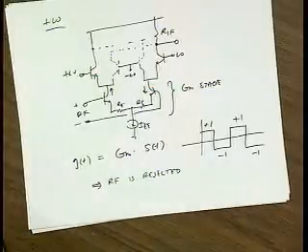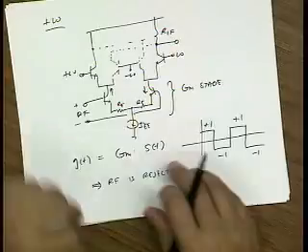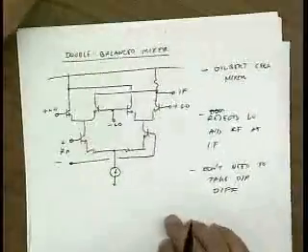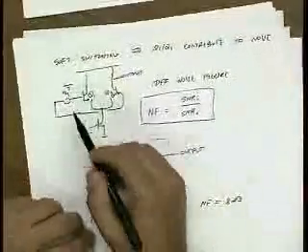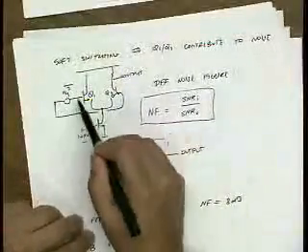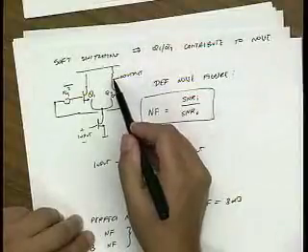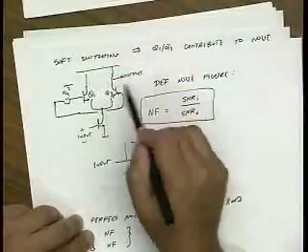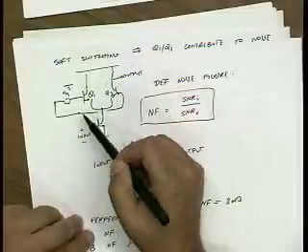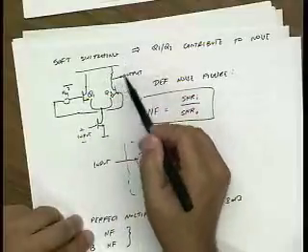Okay? Now let's see how the LO is rejected. In the single balanced mixer, let's go back a few slides. This differential pair takes my LO drive and just gains it up to the output. It's not rejected at all. It's only rejected by the output filter. Okay? So the LO signal actually modulates the output.